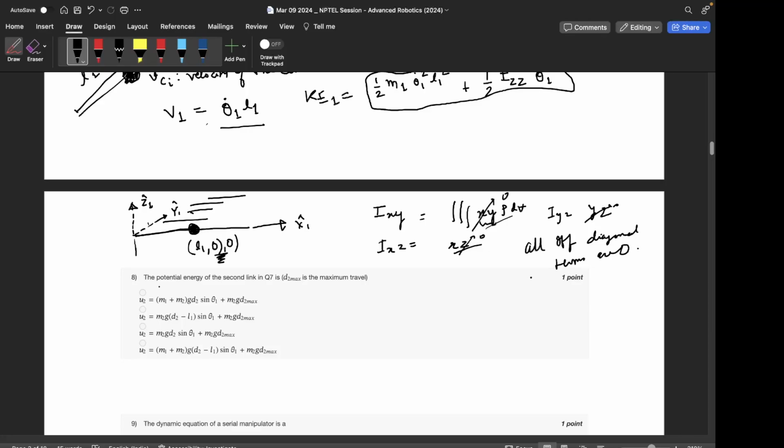Did you get it, Karthik? Yes, sir. Clear, sir. And similarly, the diagonal terms also, that is Ixx, right? Ixx was the volume integral of y square plus z square, which is again 0. Iyy, which is x square plus z square, right? And Izz, which is x square plus y square.